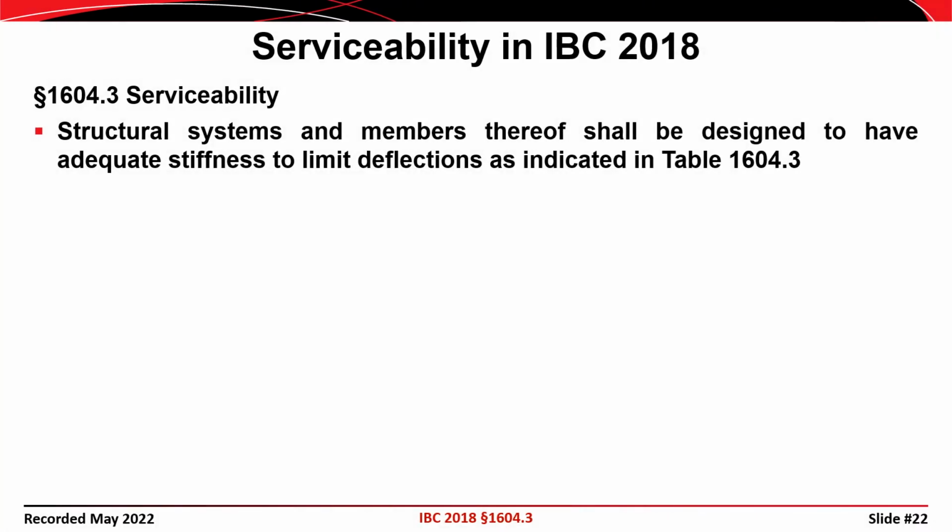Okay, we'll shift our attention to serviceability right now. The LRFD load combinations and the allowable stress load combinations don't cover serviceability. They're only for the strength design of the members. So let's look at IBC for the moment.